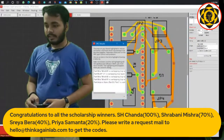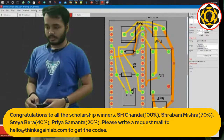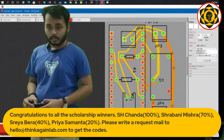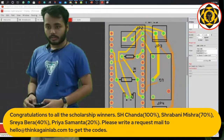Okay, see this wire, since I thickened this wire, this is touching there, right? That's why it gave me an error. But the relay unit is touching this place, right? To solve it, I will simply just do something like this. Okay. Now let's run another DRC check.